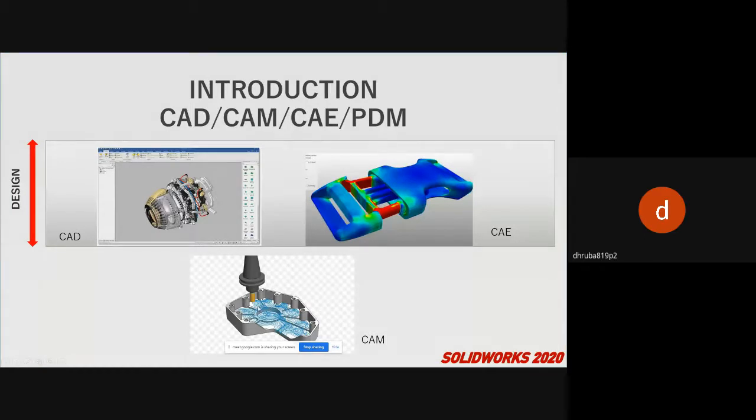If it is okay, then we'll send this CAD model to the CAM software. In CAM software, we generate the G code and M code for the part of the prototype model. Later we feed those codes to the CNC router, and the router will generate those path lines. Here you can see those path lines. This tool will move along these path lines, and it will remove metal by moving on them.